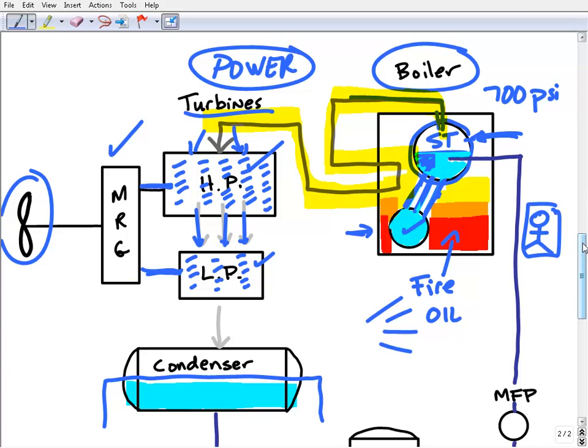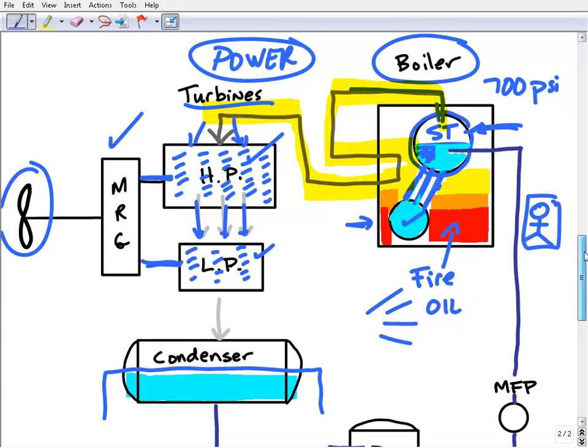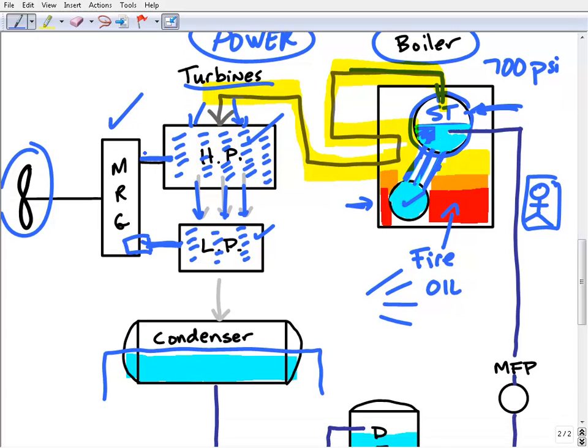Now the main reduction gear is essentially the transmission, if you will. I don't want to get too far into it because this video will take a long time, but it's just a bunch of gears, just like a transmission. You've got a couple pinions here that are spinning this whole thing, and you're taking really super fast turning mechanisms. I put RPM here. I don't even want to guess how fast they're turning, but they're turning extremely fast. And the whole idea is you have to take that and reduce that speed down, step it down, until you can turn a shaft and our propeller through the ocean.